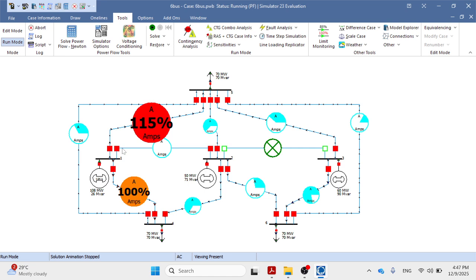And then the first zone, 80 to 90%, is very clear. Just after that, you have many choices. Maybe this one, maybe this one, maybe this one. If it's off, no need to consider it. But if it's on, you must consider that one in the same way. After that, for zone 2, you have to consider the in-feed current. Based on the regulatory, you can choose, assume this is zone 2, and then zone 3 may be coming again by another way, maybe by this one. So you have to consider the in-feed current for zone 3 also.